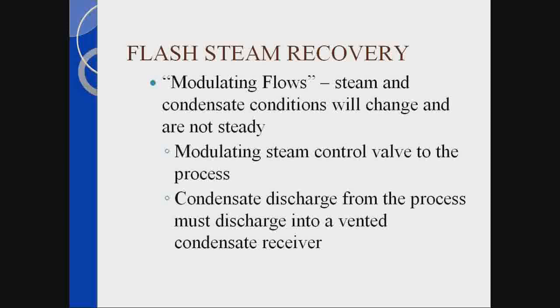The other steam process I was talking about is modulating flows. Steam and condensate conditions will change and are not at a steady state. The modulating system has a modulating steam control valve to the process because the intent is to maintain temperature of the process.